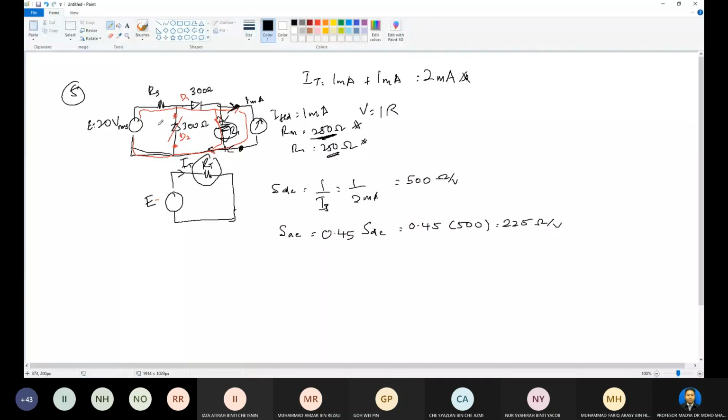So when I mentioned to you, when we assume this point to this point, to calculate the RT here, we can see from this one. That means our RT will be RS plus RD, in series, and then in parallel with these two. That means RS plus RD, this one we call the RD here, plus the parallel of R1 parallel with RM. This is R total, to get the R total here.